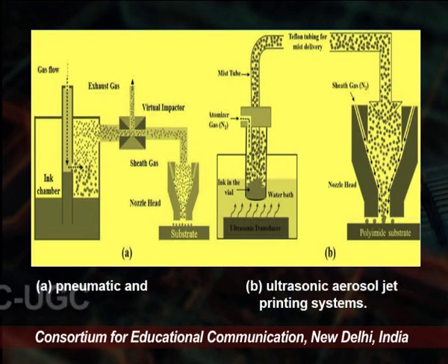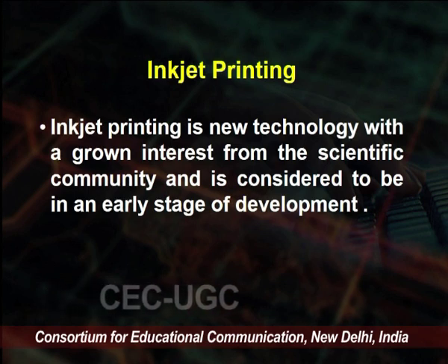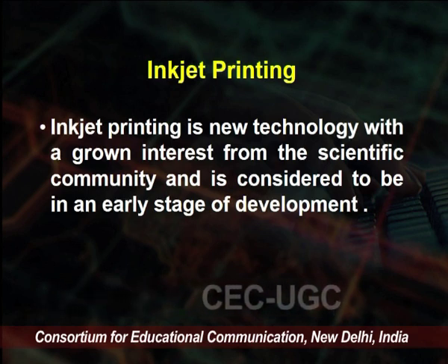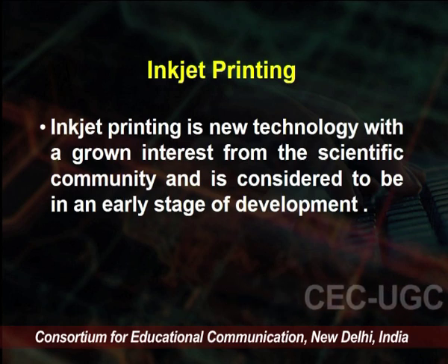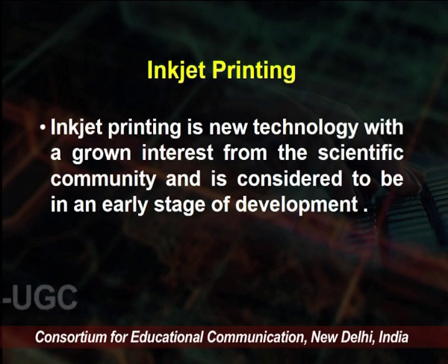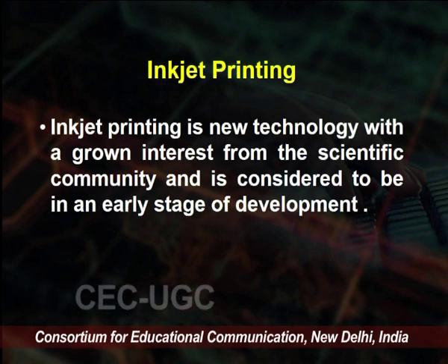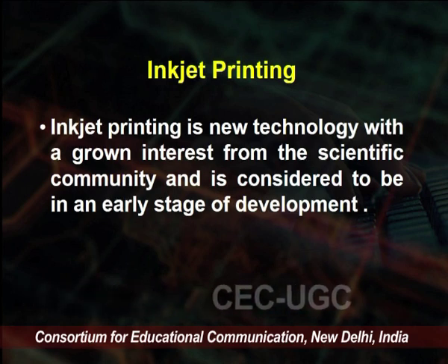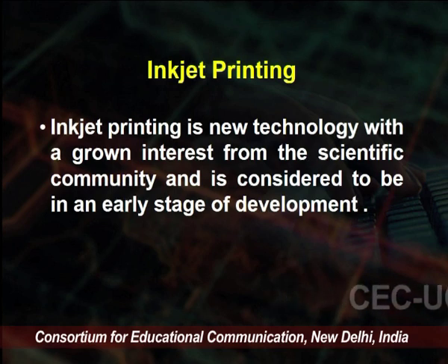You can see both sides, almost these techniques are the same, but the resolution in the ultrasonic aerosol is more as compared to the pneumatic technique. Another technique is inkjet printing. This is a non-contact technique, and inkjet is a new technology, and nowadays it is used for development of electronic devices, and mass production can be done by using this inkjet printing.